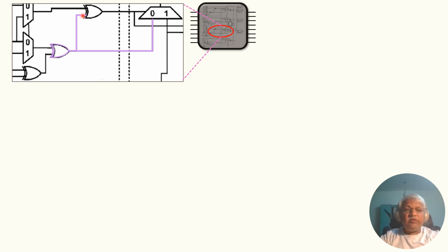So it will see a load of this much wire length, and aside from that, the input pin capacitance of this cell and the input pin capacitance of this pin. So this whole thing acts as a load. At the moment, let us consider they are within the limits.